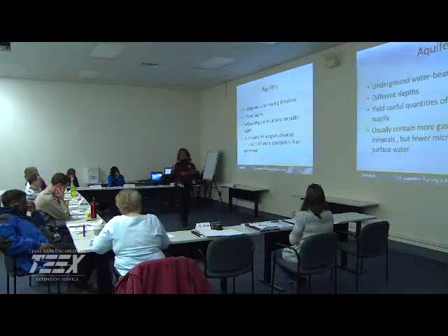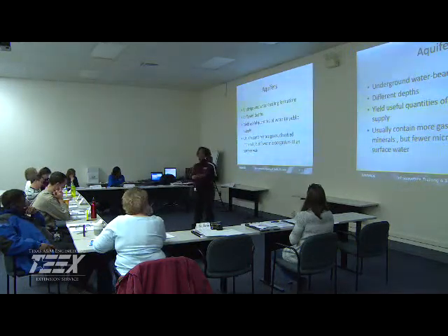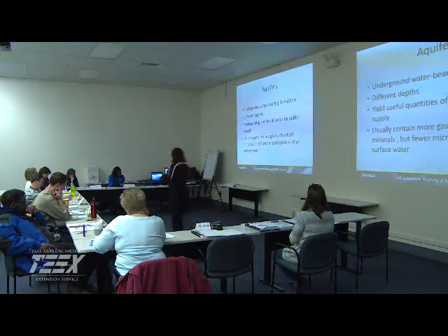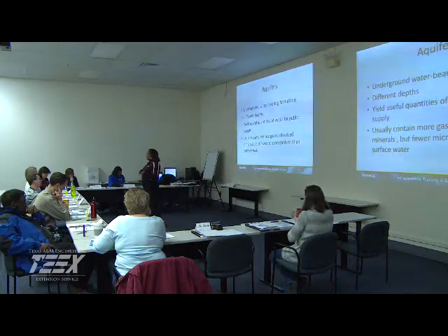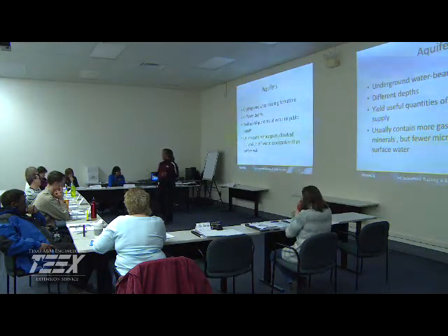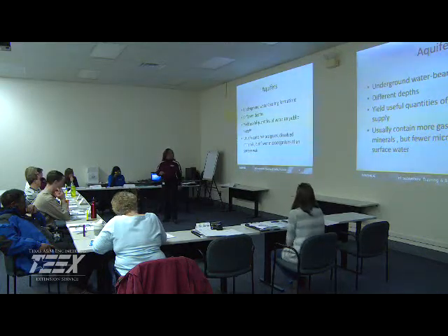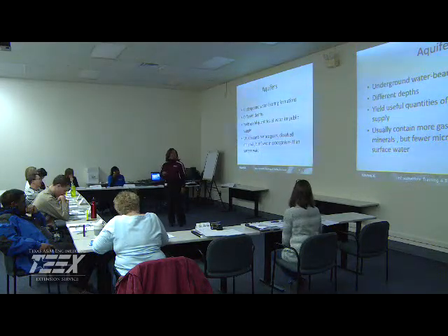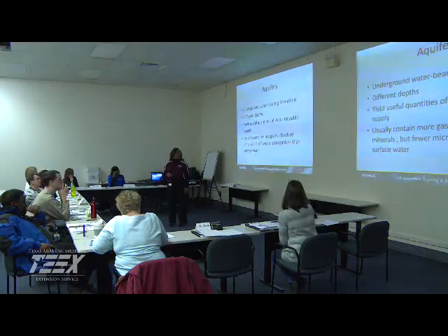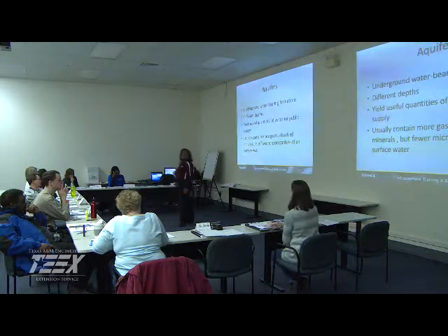Now, surface water we've already discovered will contain lots of contaminants, microorganisms, organic material, because any and everything is put into surface water. Groundwater, on the other hand, is well filtered through the ground, but it does contain more gases and dissolved minerals, because water is a universal solvent. It should contain fewer microorganisms than your surface water source.